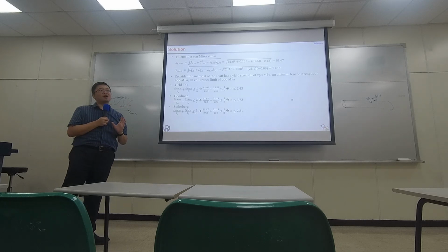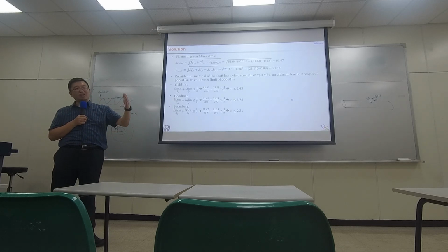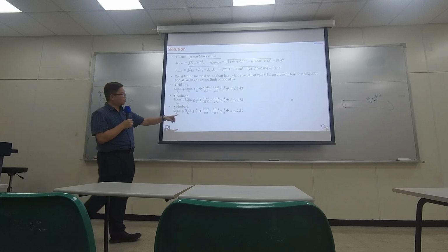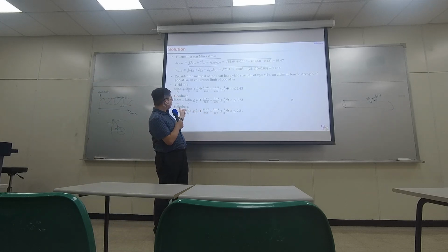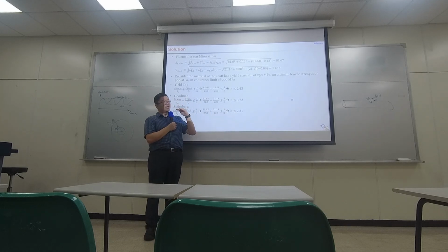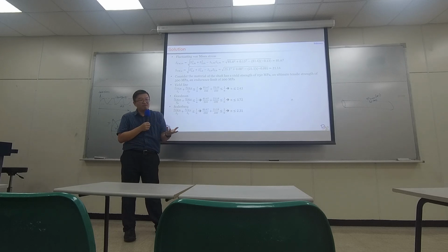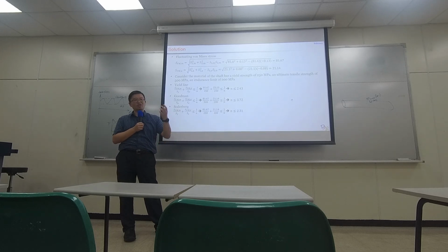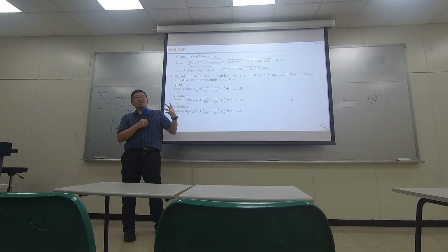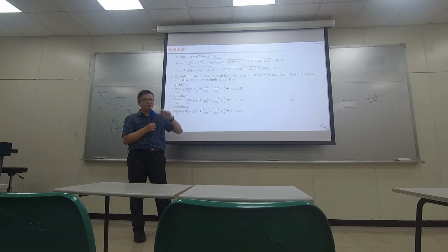So if we are very conservative, the design should tell us, right now you are having a lower safety level. So from here you can see the most conservative Soderberg model telling us your design now is having the lowest safety level. So this is how a conservative model behaves. It tends to give you a lower safety level to remind you maybe you should be safer. Okay? And what's the most aggressive model?